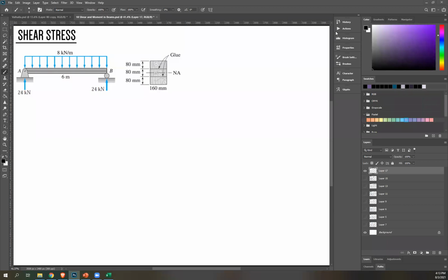To get that, we need a shear diagram. So same as before, draw your graph. This is your 0 mark. Reactions are already solved for. So from 0, we have upward, so go up by 24. This goes down, right, since it's a downward force. Since this is symmetrical, it would be pretty easy. This should be negative 24, but to be sure, we can solve as well.